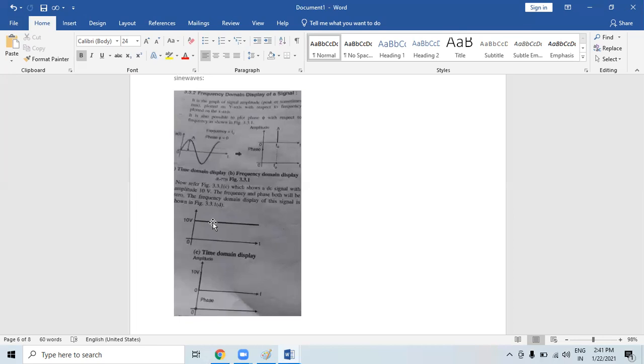So, composite signal and transmission medium. The data is generally in the form of pulses, and a pulse is a composite signal which contains many frequencies. Note that the particular shape of a pulse is due to the sum of specific frequencies at specific amplitude and phase. If there is any change in the amplitude or phase of these frequency components, then the shape of the pulse will not remain the same.